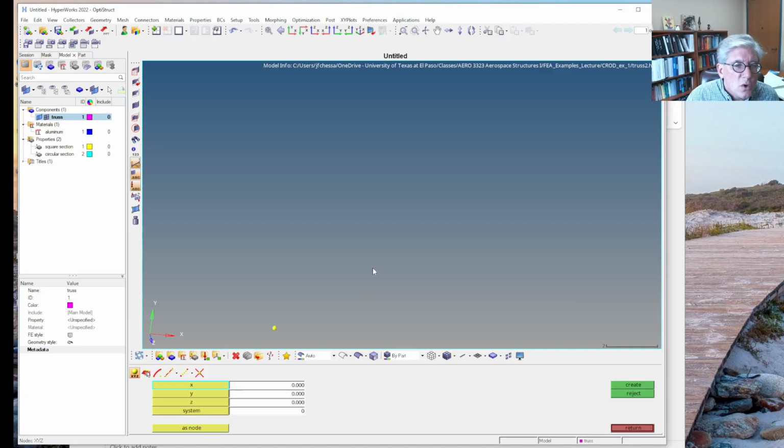If you do Control and the middle mouse button, you can do a zoom, and you make this little window and it zooms in. If you do Control and the scroll wheel, it'll zoom in and out, and then Control and the right mouse button, the third mouse button, it'll pan. Okay. Also, you can use these. So I'm going to look at the default XY position. So you'll get used to it, right? You can also toggle them here.